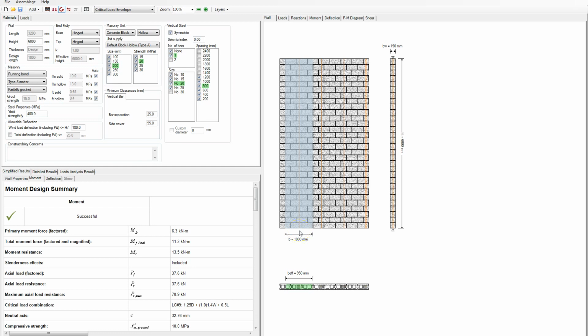So you need to divide that 760 by 0.8 to get the 950 divided that you see there. So I just quickly did that on my calculator in front of me. So yeah, 760 millimeters divided by 0.8 meters, which is the spacing, that gives you the 950 that's shown here. That's another common question that we get quite a bit.